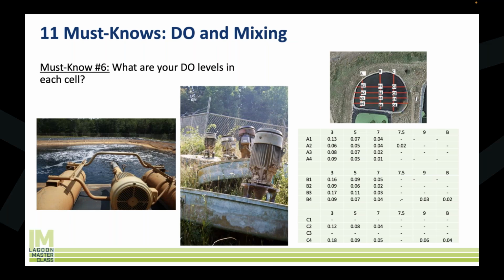What I could say is a very, very common thing that I've seen, along with sludge, is broken aerators sitting on the banks of a lagoon. Or even if you have a diffuse system, broken diffusers, or geysers coming up from a header that's broken underneath the water. All these things obviously have an impact on your dissolved oxygen and subsequently your mixing. So what I usually recommend is while you're doing your sludge survey, you're doing a DO survey as well. Well, a DO, temperature and pH survey as well.